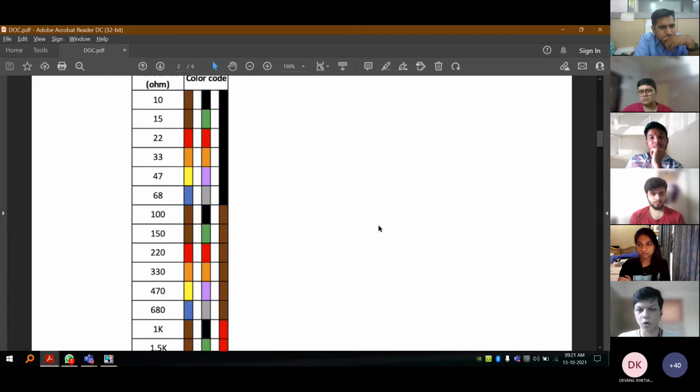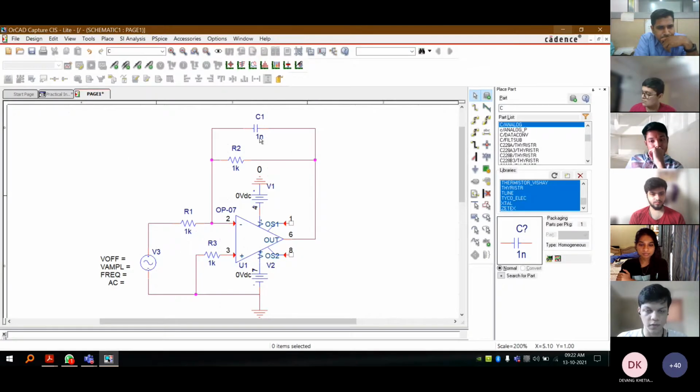But the moment you move to in-person college, which I know probably none of you want to, when you do that, you're going to have to get used to using resistances and capacitors of very specific values. So you have to get used to combining maybe 4 different resistors to get the resistance value that you want. So it's best that you get used to that, right? So we're going to be using these standard values. As you can see, 33 is a standard value. So that means we're going to have 3.3 kilo ohms, and so we're going to have 33 kilo ohms by extension. Right. So now we can move back to our circuit, and we give all of the values that we want.